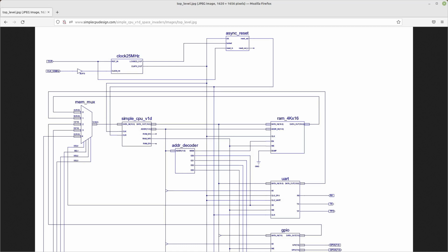And the goal here is, once you've got a good understanding of the software library, you can go away and write your own games. Obviously, the hardware is fixed. There's no need to change the hardware. All we need to do is reassemble our program, and we can use the Xilinx command tool, data2mem, to modify the pre-synthesized bit file with a different program.